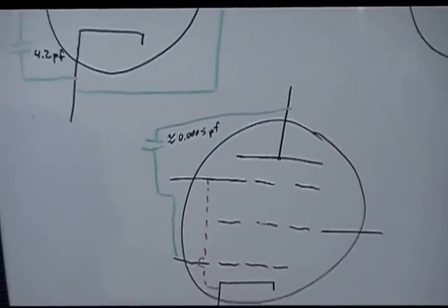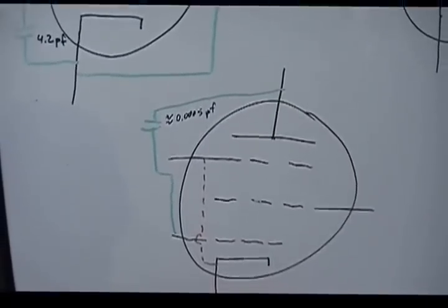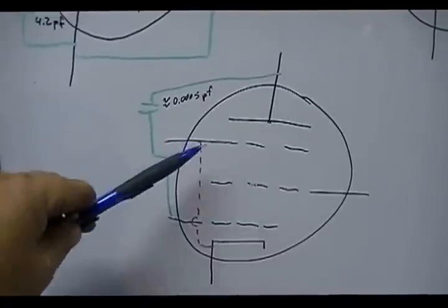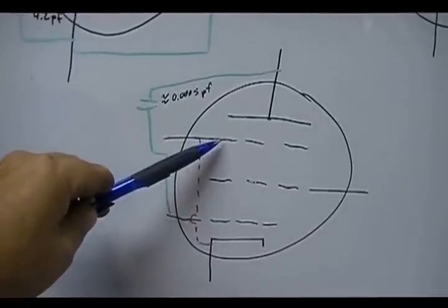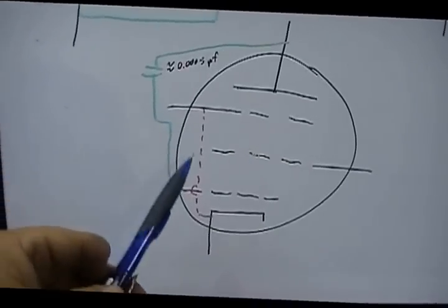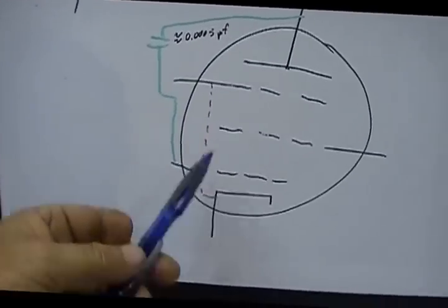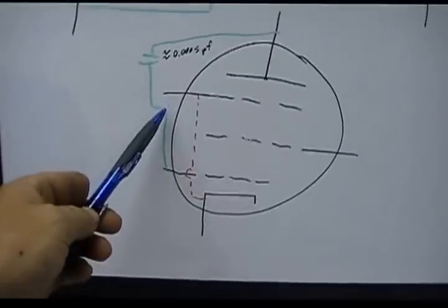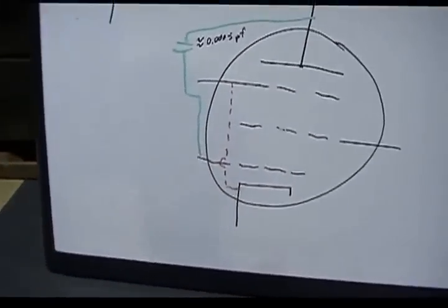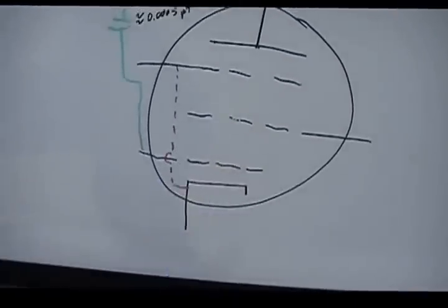And then by doing so, it's called the suppressor grid. It suppresses secondary emission. And the way it does it is by hooking it to a negative, either ground, cathode, or something. Now, like I say, a lot of them are actually interconnected. There's no tube pin here, but there are some that do have one, so I wanted to show it. Now, the way it does that is just because the fact it is negative.